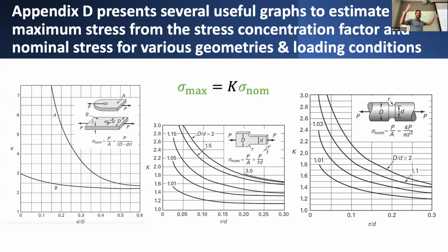But if we have material constraints, where the maximum stress can't exceed some value, all we need to know is the average stress, which we can reasonably estimate using force divided by area, and the stress concentration factor, something somebody else came up with, put into some nice tables, and we can use directly.